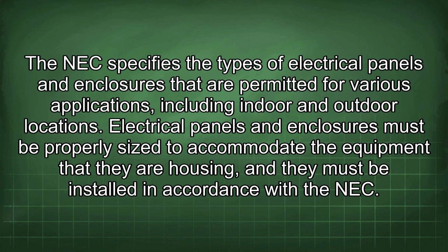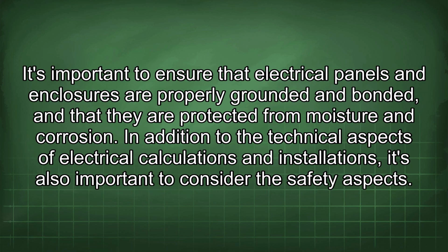Electrical panels and enclosures must be properly sized to accommodate the equipment that they are housing, and they must be installed in accordance with the NEC. It's important to ensure that electrical panels and enclosures are properly grounded and bonded, and that they are protected from moisture and corrosion.